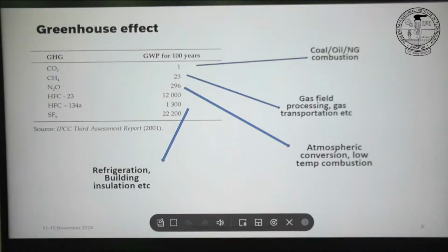At 2000 degrees, the nitrogen in air will also react with oxygen to produce nitrogen oxides. So it will not stay inert. Normally we always learn in our undergraduate course that nitrogen is an inert gas, so what comes in goes out. But in reality, a very small fraction of nitrogen also reacts with oxygen and generates these NOx. During the combustion, the NOx which is generated is NO and NO2. It's not N2O. If you have combustion at low temperature, you can also have N2O.